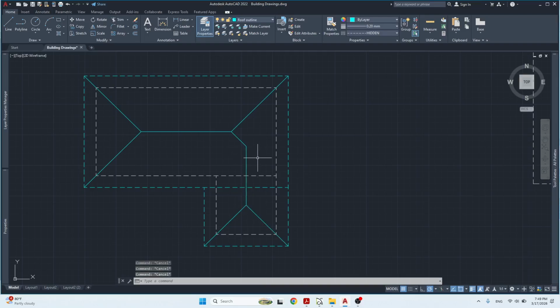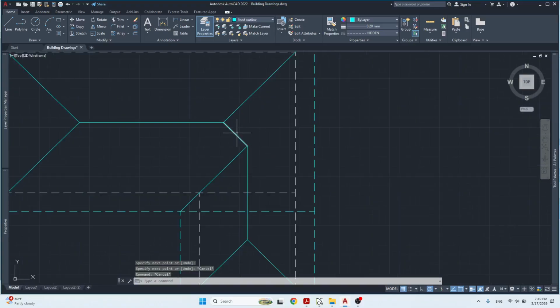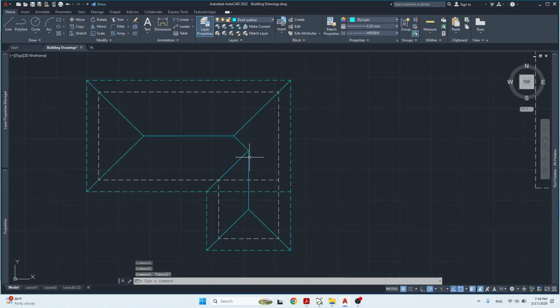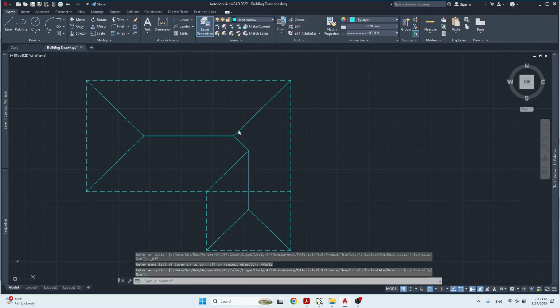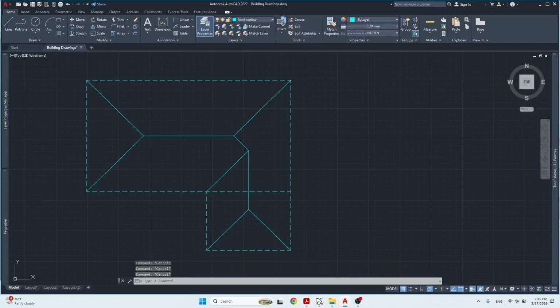Okay, so all we need to do now is just put in our valley rafter right there, and notice it meets at the same point where this hip meets the ridge. The valley, hip, ridge all meet up at that point. And let me just turn off the wall layer so you could better see what we're talking about. Let me just trim these out.